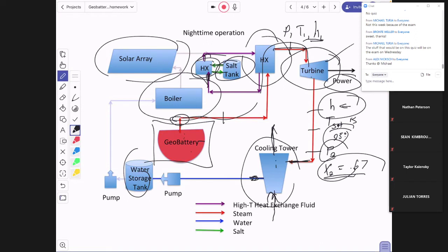And you should understand how you get that power, and what energy in or energy out is necessary to get a particular change of state that we might want, going from one place to the other. For instance, how much heat do I need to put into the boiler to get a mass flux of water to be turned into steam at a given temperature and pressure, right? And that's pretty simple. We already know what that is, right?